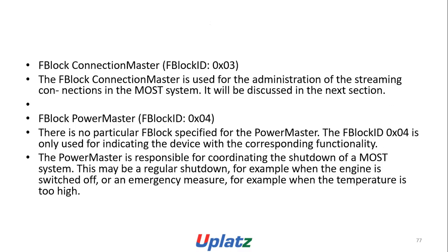Fblock connection master, Fblock ID 0x03. The Fblock connection master is used for administration of the streaming connections in the MOST system. It will be discussed in the next section. Fblock power master, Fblock ID 0x04. There is no particular Fblock specified for power master. The Fblock ID 0x04 is only used for indicating the device with the corresponding functionality.